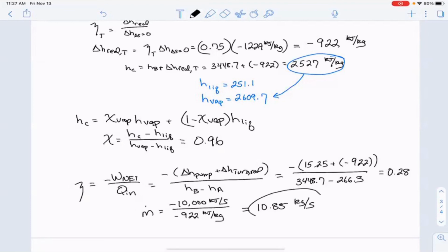So this 10 kilogram per second might require a larger pump than the adiabatic reversible case, or the size of the heat exchanger, which could, like I said, be a river in the last lecture, might need to be larger in order to provide that flow rate. So there are a number of interesting ramifications from a design perspective that occur as the efficiency goes down.